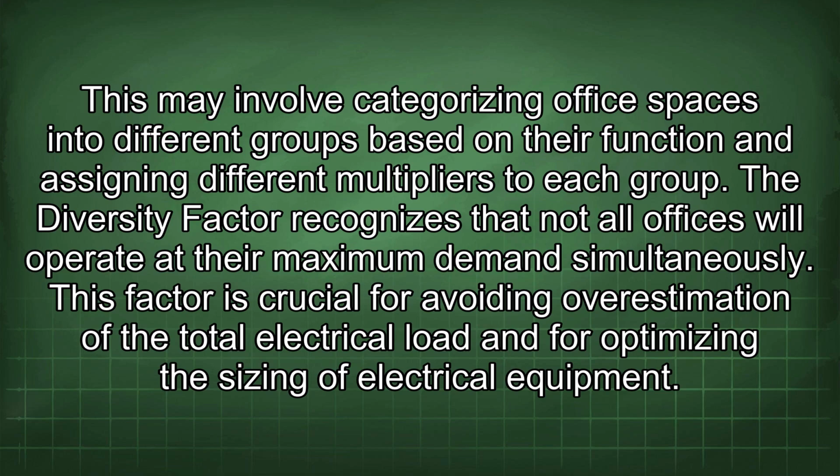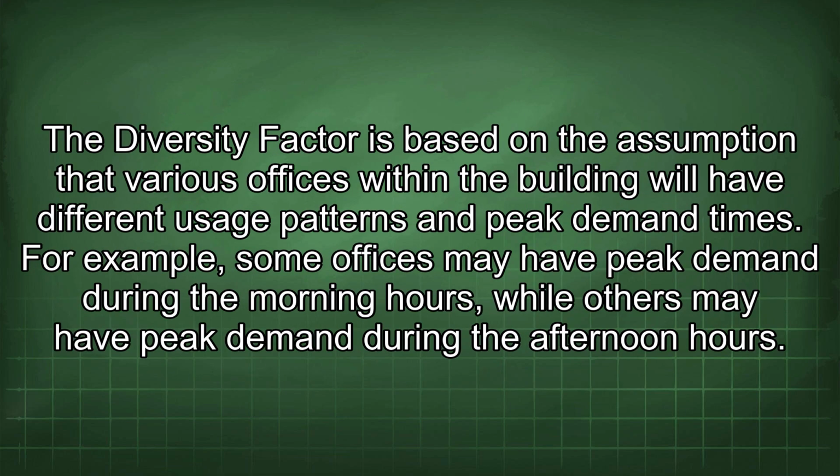The diversity factor recognizes that not all offices will operate at their maximum demand simultaneously. This factor is crucial for avoiding overestimation of the total electrical load and for optimizing the sizing of electrical equipment. The diversity factor is based on the assumption that various offices within the building will have different usage patterns and peak demand times. For example, some offices may have peak demand during the morning hours, while others may have peak demand during the afternoon hours.